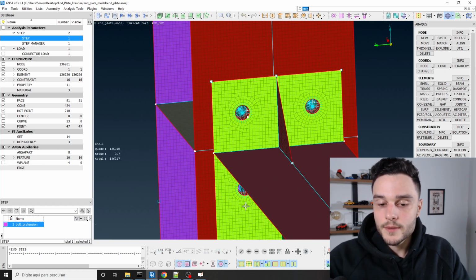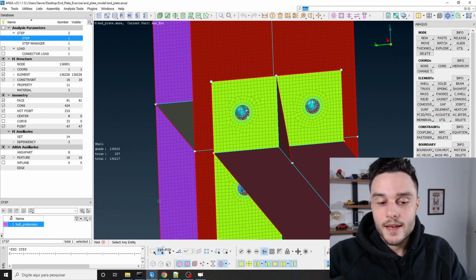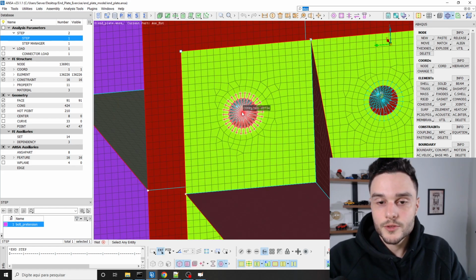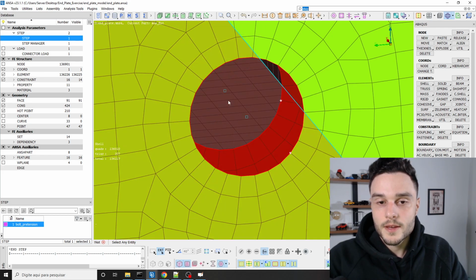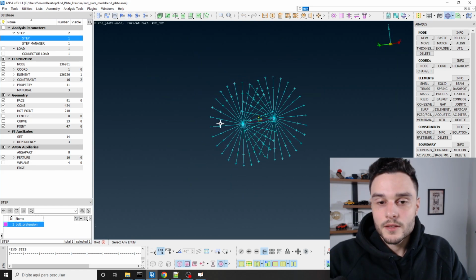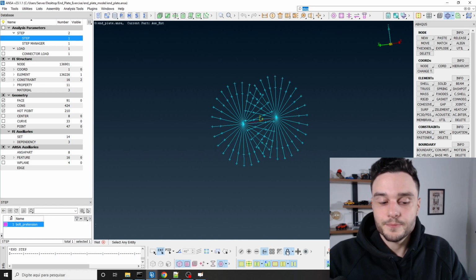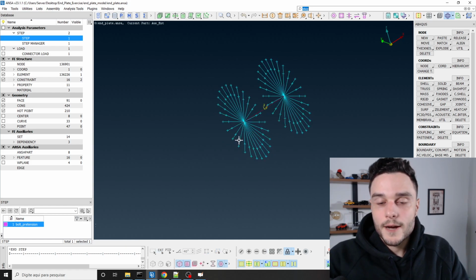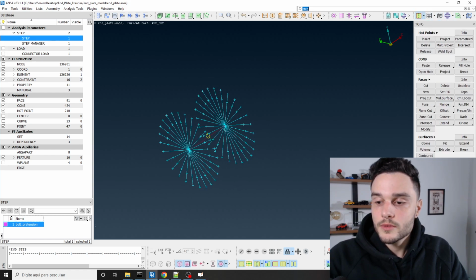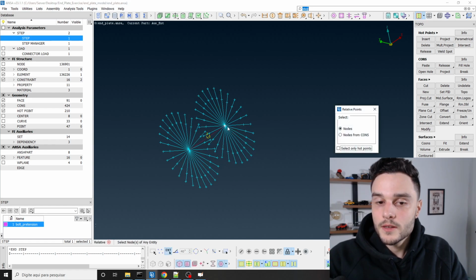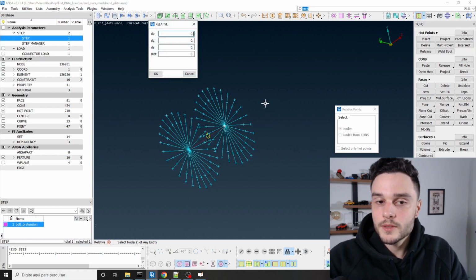So again, let's use the NOT tool to isolate entities. Select entity selection mode, zoom in here, select this coupling, this beam, and this coupling, middle mouse button, lock this view by clicking here. Now let's go to classic topo module, use relative tool, select this, middle mouse button, select this and this. Define as 2, click on OK.